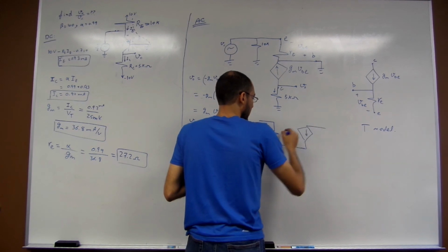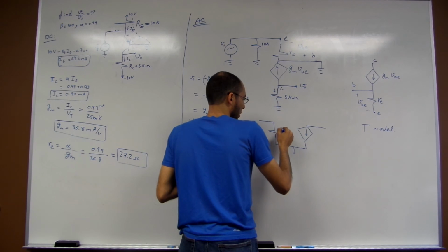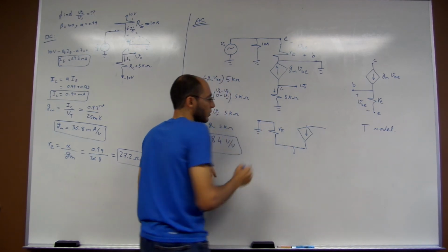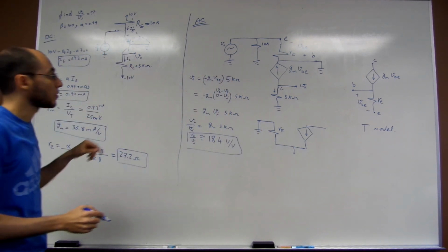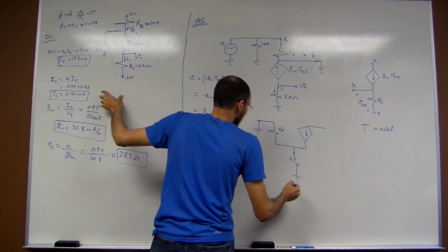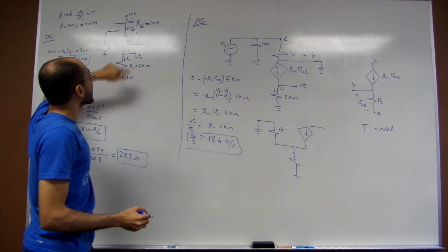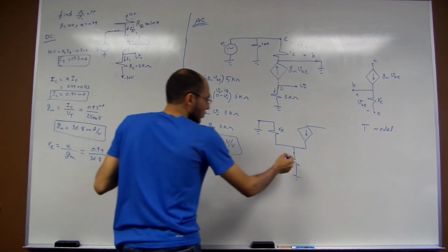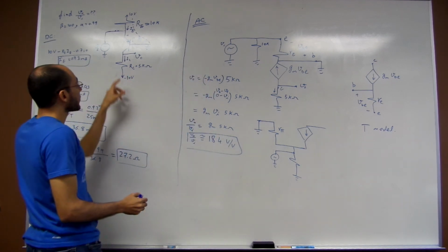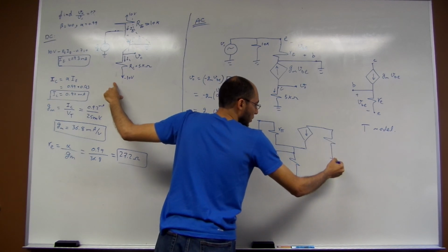that is the current source, and that is the emitter, and this is R pi. The base is connected to the ground. The emitter has a resistor, and then to the ground, and the emitter has an input source. So that is the input source. While the collector has a resistor and then to the ground.